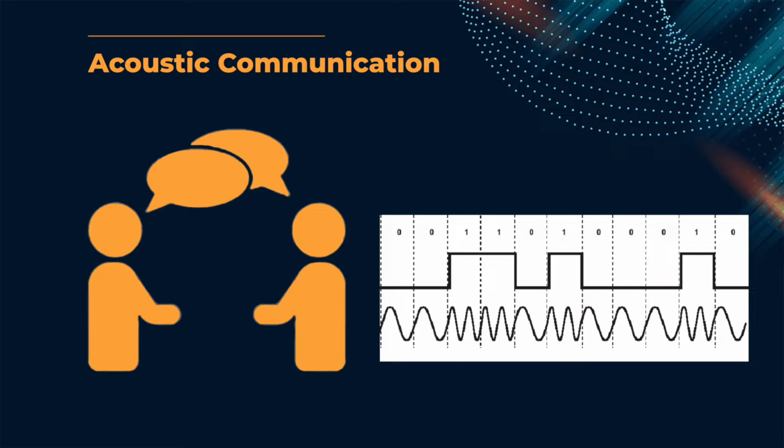Instead of using words, in the case of a digital communication system, I will translate that to ones and zeros. And those ones and zeros will get translated to a frequency. So let's say I can use two frequencies to represent 0 and 1. If there is a 0, I transmit one frequency. If there is a 1, I transmit the other frequency. And that's what we call FSK, or frequency shift keying, and that's about it.